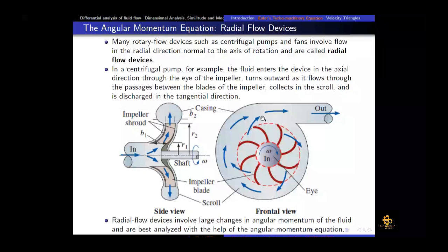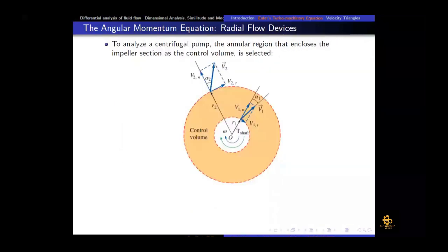So it is a kind of diffuser arrangement. In a diffuser, the velocity decreases due to the increase in cross-sectional area, and if the velocity is decreasing, you know that the static pressure increases. We need higher pressure so that it can travel against gravity towards the overhead tank. It is just to give you an idea. We will do these things in detail.